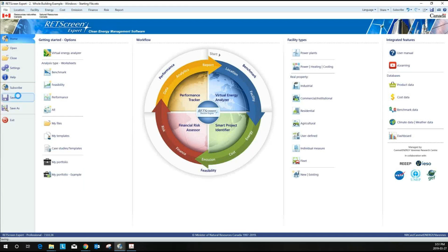So I've actually done a little calculation here on demand control ventilation. We'll reduce the temperatures in the building first by 1 degree with a set point, but then we'll put in place a speed control to change the speed of the fan in the exhaust and supply system.